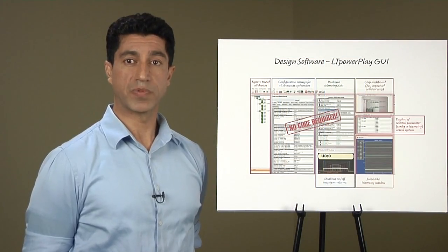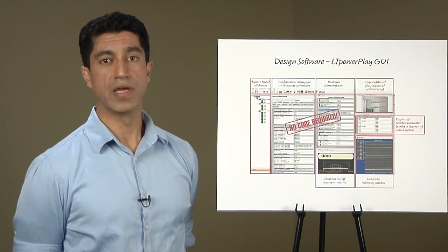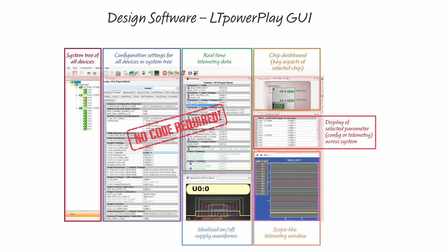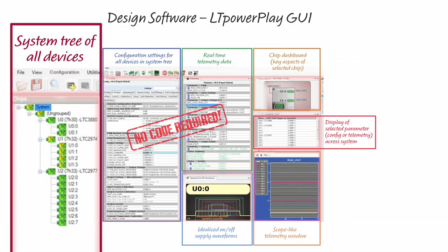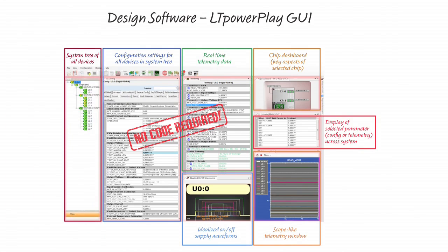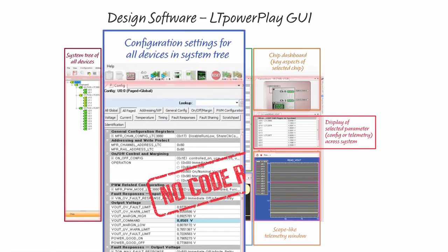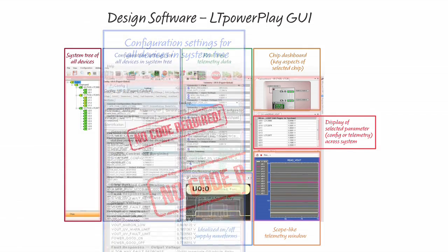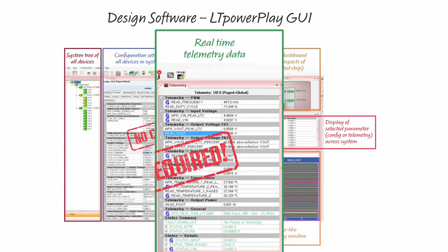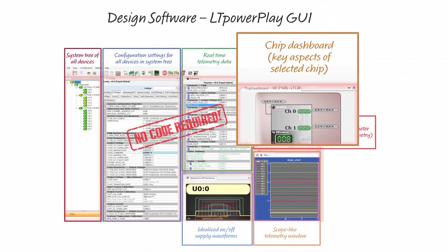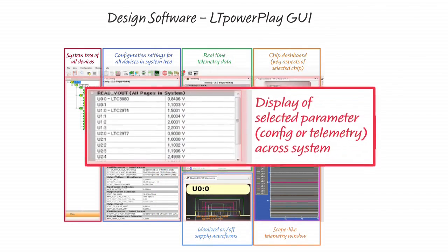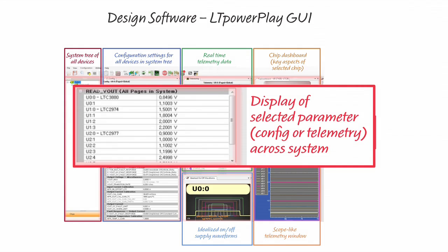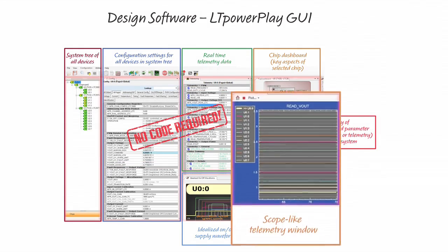Digital power system management products are configured and monitored via a 2-wire PMBus interface and open I2C based digital interface protocol. This enables seamless integration with existing embedded systems and architectures, board mount controllers, BMCs, and intelligent platform management interface, IPMI, functions. For simplicity and ease of use, especially at the earliest stages of hardware development and testing, a graphical user interface, a GUI, running on a PC is used to communicate with the PSM device through a USB to PMBus adapter board.